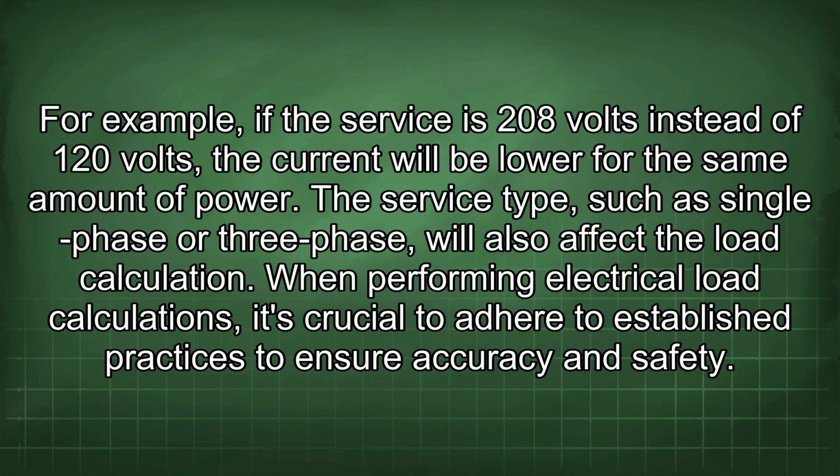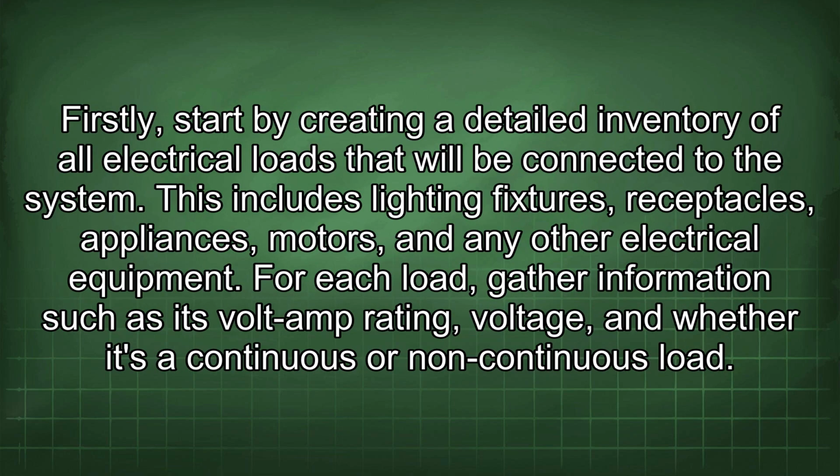When performing electrical load calculations, it's crucial to adhere to established practices to ensure accuracy and safety. Firstly, start by creating a detailed inventory of all electrical loads that will be connected to the system. This includes lighting fixtures, receptacles, appliances, motors, and any other electrical equipment. For each load, gather information such as its volt-amp rating, voltage, and whether it's a continuous or non-continuous load.